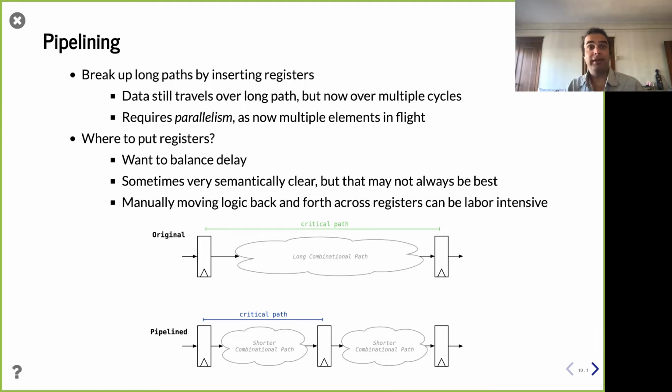Fortunately, most hardware design is not that bad. For example, if you're doing something involving video, on different cycles you're going to have different pixels, right? And depending on the operation you're doing on those pixels, they may be completely independent. Easy to get that parallelism. And you can choose: I have a lot of parallelism, and I need to process a frame of 4K video, millions of pixels.